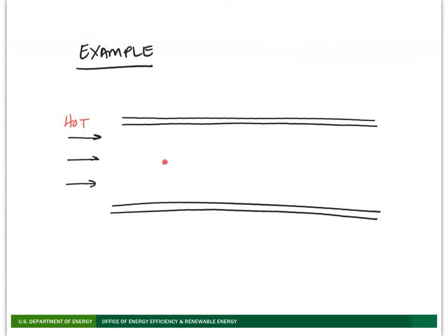transfer? We should have the warmest temperature in our duct system near the inlet of the duct, but also near the center of the duct, because that's where we should have relatively fully developed flow behavior. The next temperature in the system is going to be right at the edge of the duct wall, but we're going to have some heat transfer across the duct wall, and then we're going to have another temperature, depending on where your duct is located, in the air outside or around the duct.